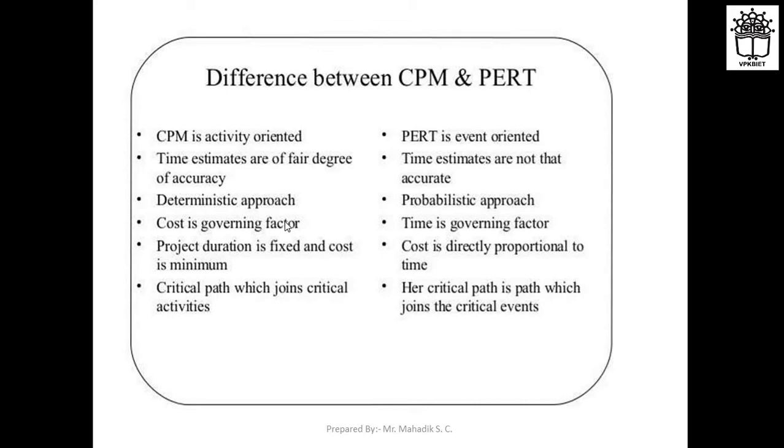In CPM, the critical path joins critical activities, whereas in PERT the critical path is a path which joins the critical events. So this is the difference between CPM and PERT.